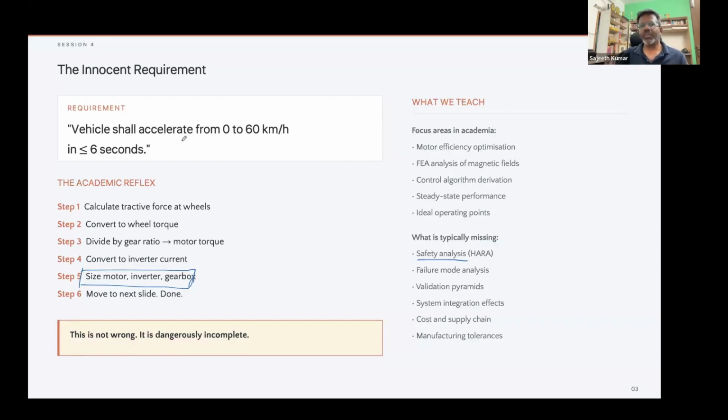We'll need to tell them, okay, the vehicle will go from 0 to 60 kilometers per hour only if the throttle is pressed. I mean, of course, that goes without saying. But even if the throttle is pressed, suppose knowingly or unknowingly someone touches the brake, then none of it will happen. It should basically shut down. You should not give torque.